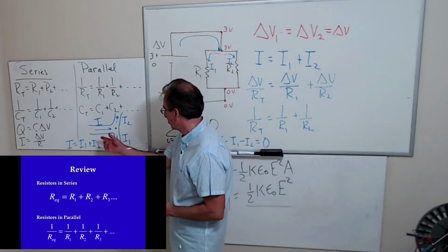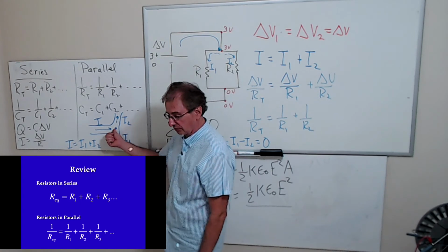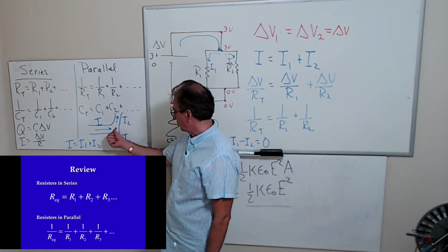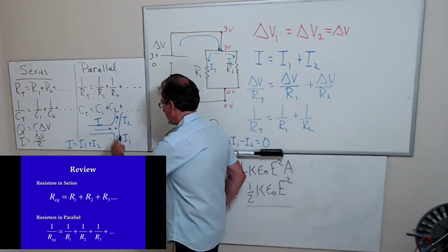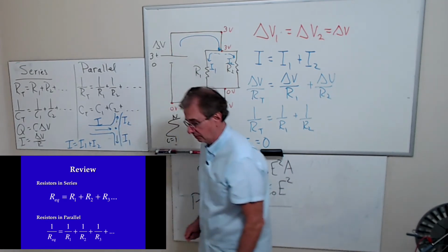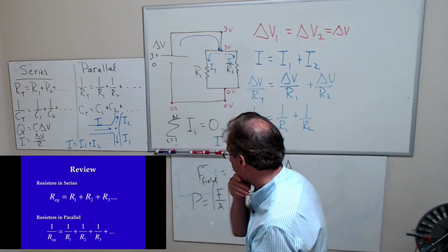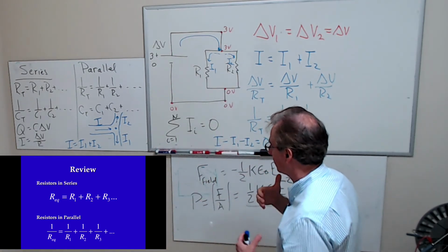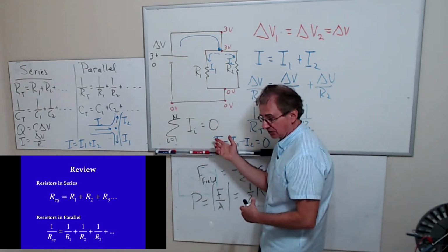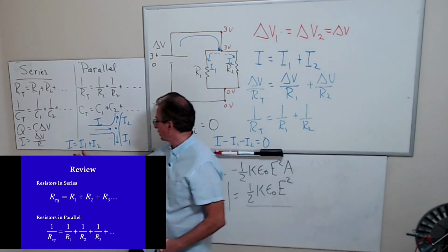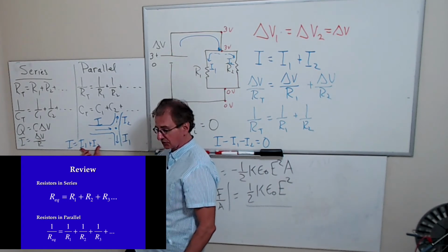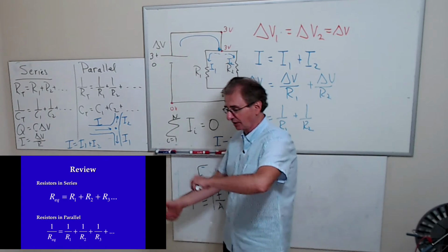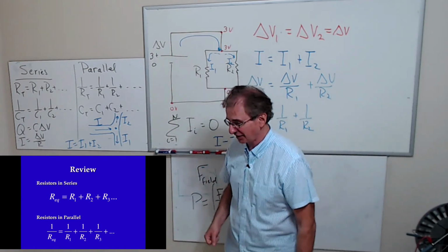So your indices is all the currents that are going through this node. Okay, it's everything that's going through there. So this is going through it and then this is coming out. And so that's what that represents. That's why I can write it as this summation, or I can say the sum of the currents entering a node equals the sum of the currents leaving a node. It's the same thing. All I'm doing is putting the terms on the other side of the equation.